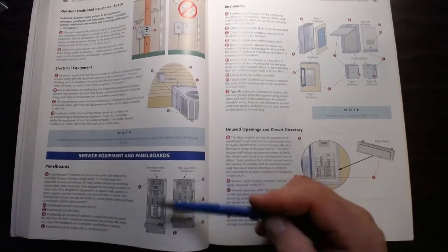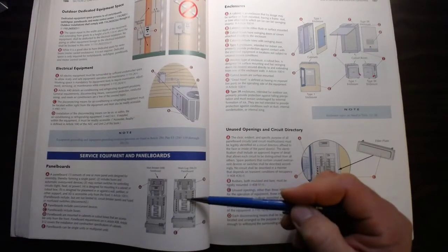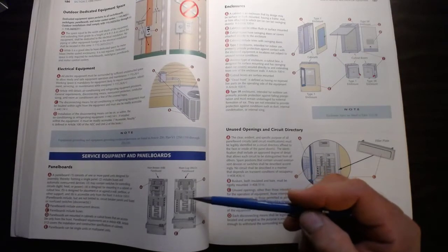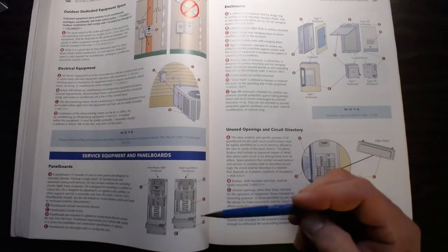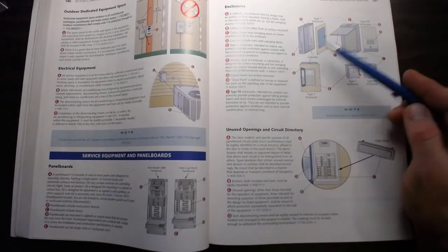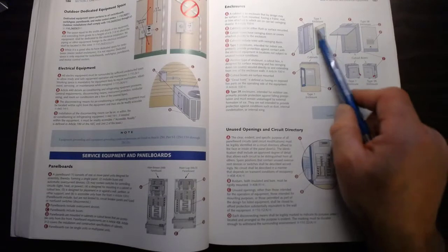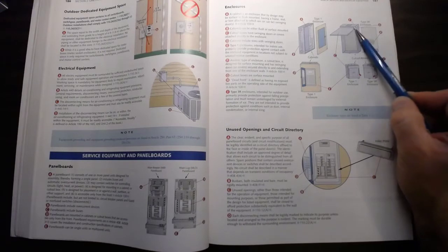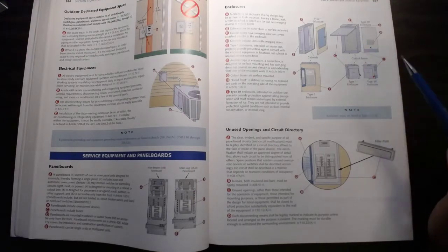Let's quickly touch on what panel boards are. The panel board in this case would be a main breaker or a main lug. In this one, there's no breaker at the top; it's just lugged in. A panel board includes overcurrent protective devices. It includes busing, and is usually mounted inside of an enclosure. When we look over here at the enclosures, we see there are different types. We have a NEMA Type 1 inside-only enclosure, and we have a NEMA 3R rain-tight enclosure here. So you see the doors will open differently. They open from the top with a drip edge here to ensure that when it rains, no water gets into it when it's closed.